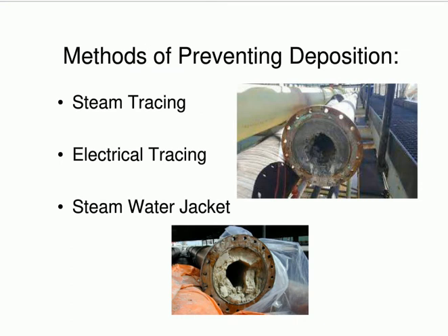Methods of preventing deposition, and that's really what this lesson is all about, and we are probably making our 45 minute aim. We've got steam tracing, electrical tracing, and then a steam water jacket. Okay, so that's preventing deposition. The whole idea, again, you can see the deposition takes place.